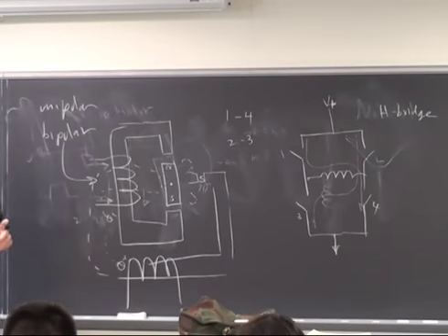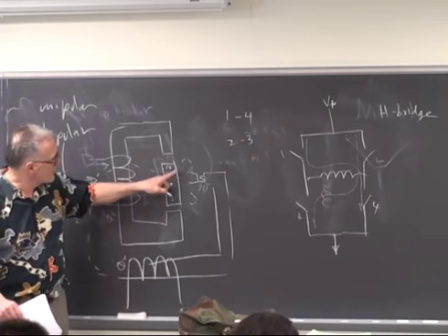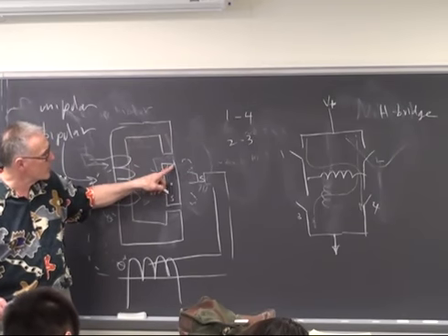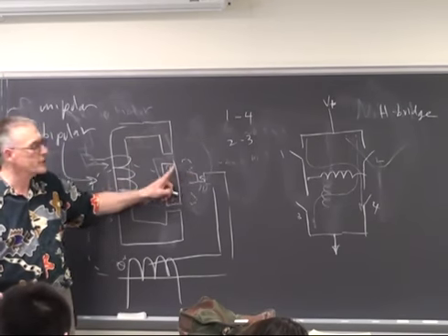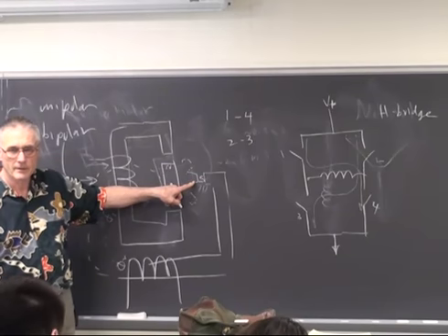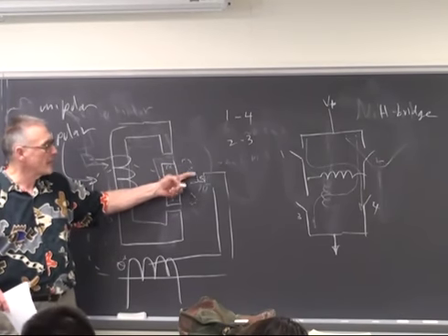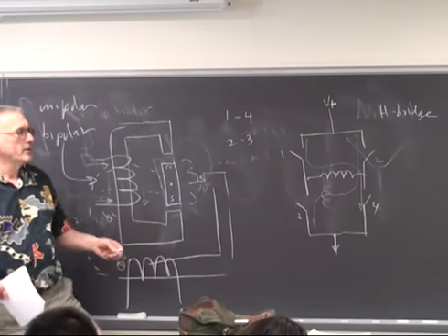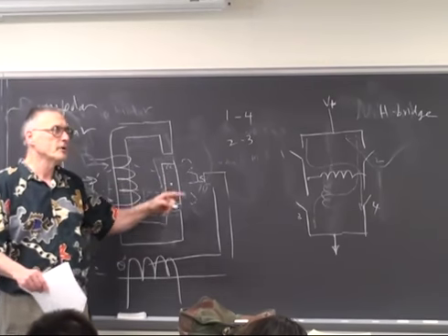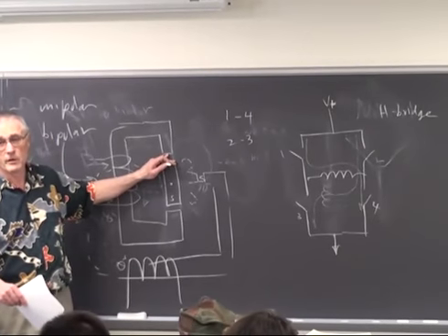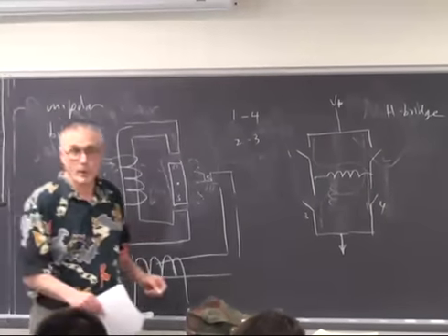This is a low torque alternative. And the reason it's low torque is that when you turn this magnet off and turn this magnet on, the pole piece is quite far from here, and so the attraction is not great. So the torque generated is quite time variable. The alternative is you turn this coil on, as I said before you turn this coil off, which is called a full step.